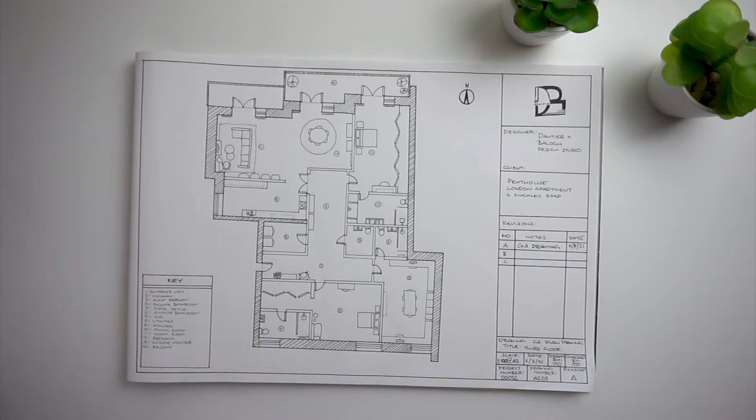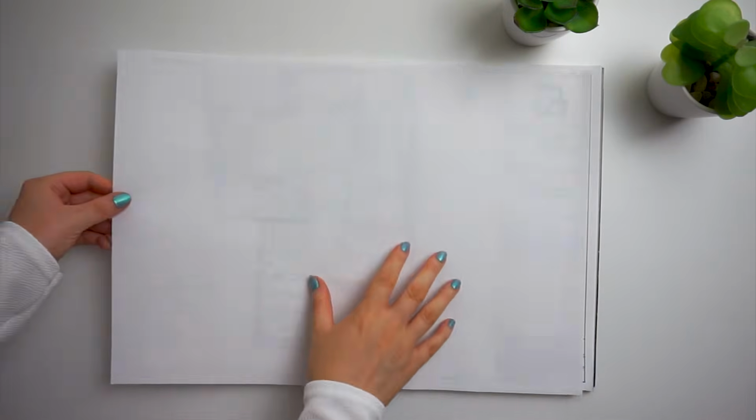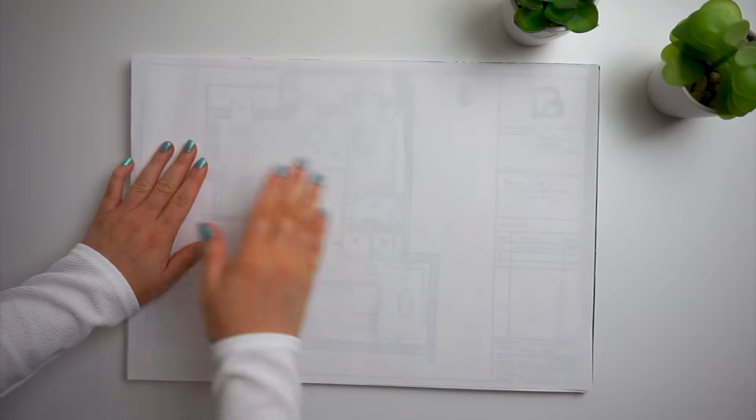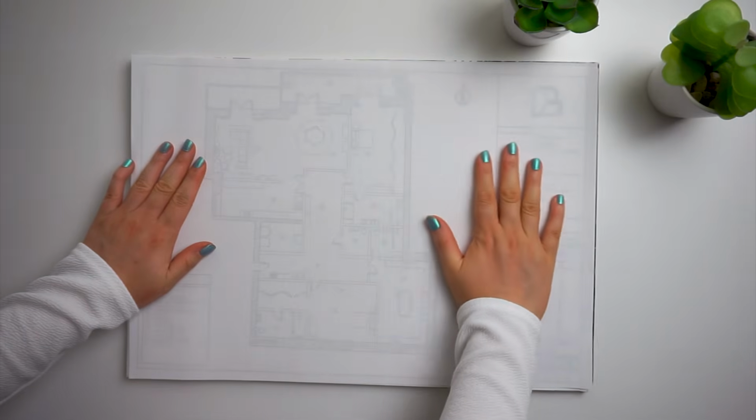With floor plans you would also add dimensions onto the drawing. I would draw all the dimensions for the walls, furniture, fixtures, but I would definitely do them on 3 separate pieces of paper. Definitely don't mess up your lovely floor plan you just sketched out. And the easiest way to do that is by using a piece of layout paper and tracing over the original plan drawing you did beforehand.